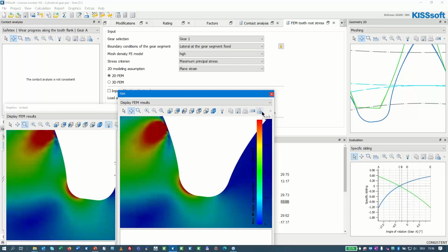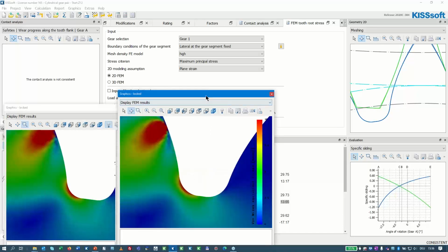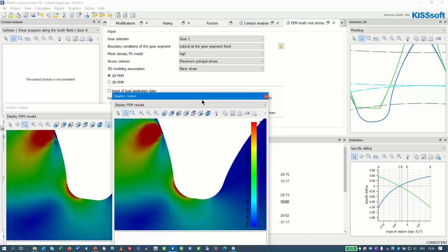So overall, we are seeing a confirmation in principle. The higher the radius, the lower the stress. That's fairly obvious. But frankly, I'm a bit disappointed. It's not that much improvement. Now that we have improved the radius, but we have kept the type of curve, the toroidal fillet, let us try another type of curve.